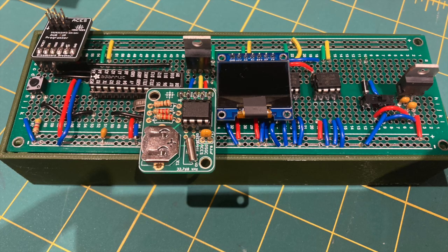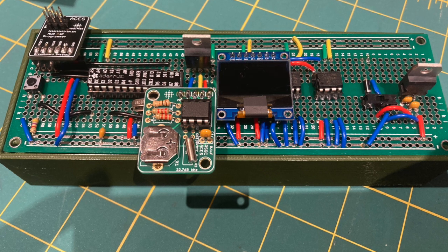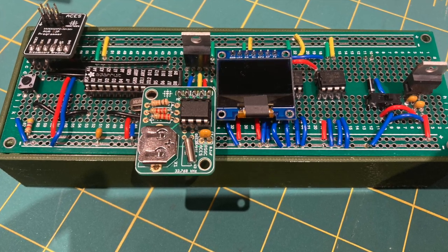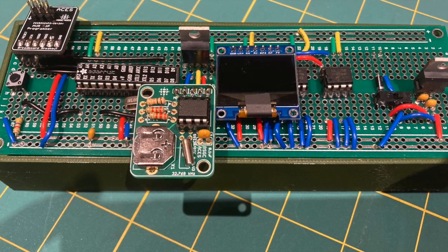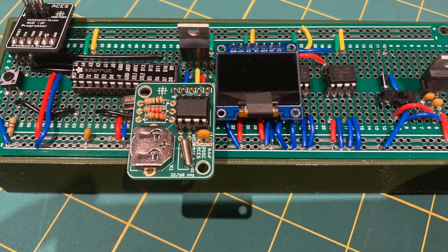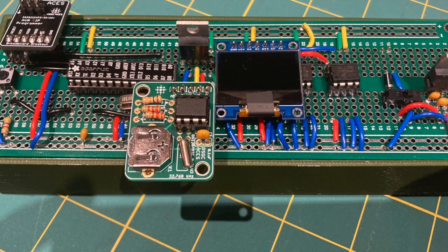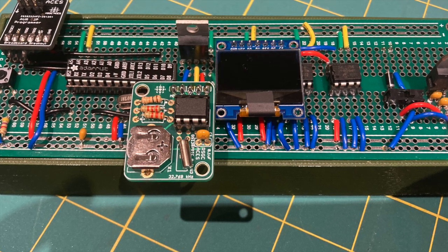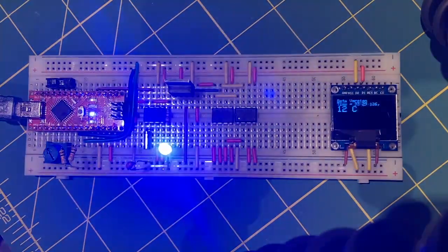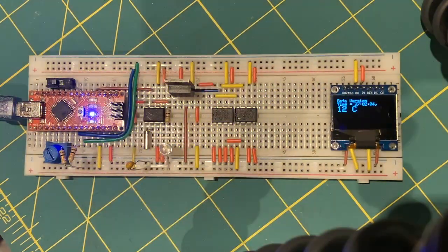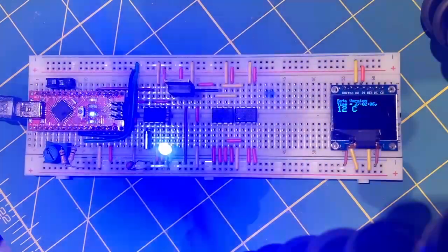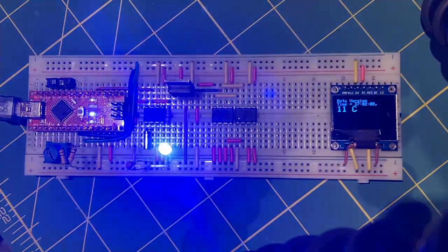For starters, the exterior design intended to have a permaproto board 6 inches long attached to a 3D printed case. However, the permaproto board was really bad quality, and the components used to connect the appliances to the permaproto board were also really bad quality, and the system did not end up working. It does work on the breadboard, so we'll use these components as the example. On the Arduino Nano, the serial data and serial clock lines are designated as pins A4 and A5 respectively. Two of the long breadboard rails were designated for SDA and SCL rails.